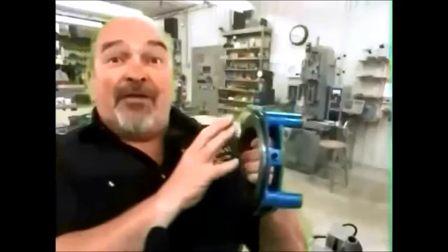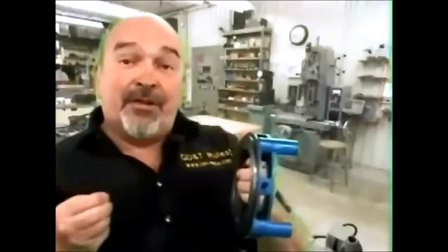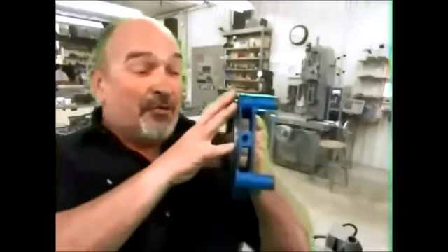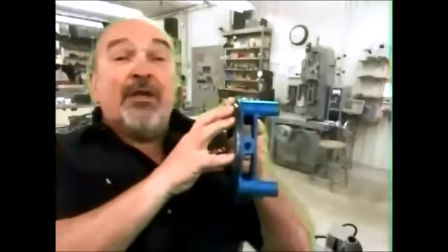We're able to modify the pilot diameter at MMC because as the pilot diameter is produced nearer to its smallest size, it's allowed to shift a bit in order to get the screws to assemble. If our supplier treated the datum shift like a bonus tolerance, the clearance holes could be out of position more within the pattern. As a result, we might have to shift the part one way to assemble a couple of the screws, then take those screws out so we could shift the part the other way to assemble the other screws. This tip uses a simpler assembly to illustrate the point.